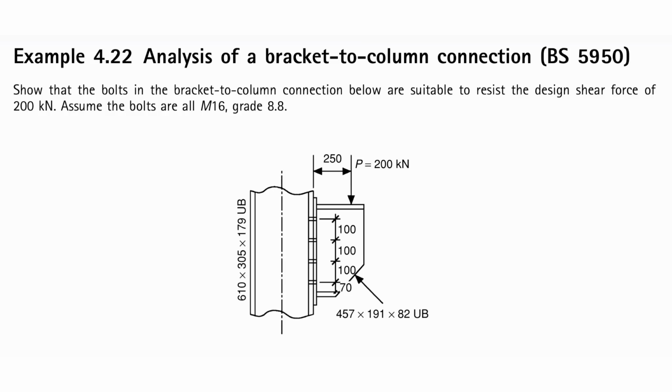In today's lesson, we are going to analyze a bracket to column connection, and the question is: show that the bolts in the bracket to column connection below are suitable to resist the design shear force of 200 kilonewtons. Assume the bolts are all M16 grade 8.8.